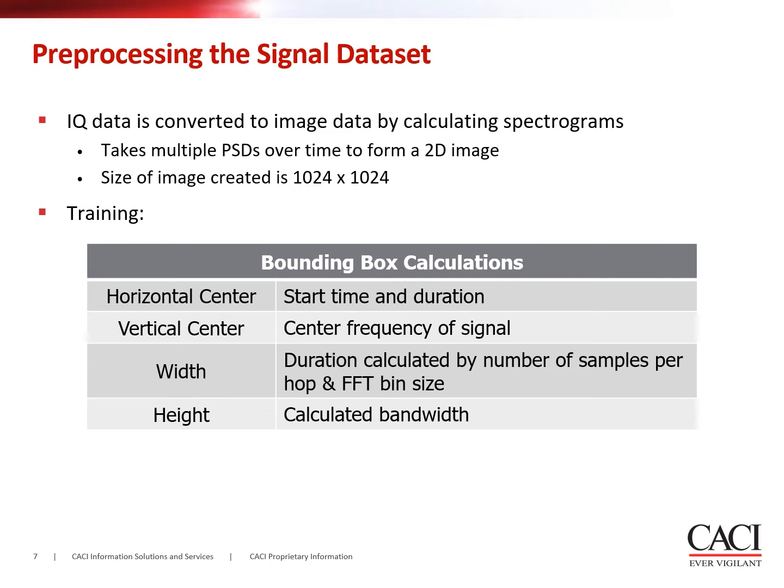Additional preprocessing was needed to prepare the data for Study 2, which used YOLO to detect a frequency hopper in an environment with interferers. To create an image that contained both the signal of interest and interferers, the spectrogram images were stitched together. The signal of interest was randomly placed in the stitched image in order to vary the frequency hopper over frequency and time.